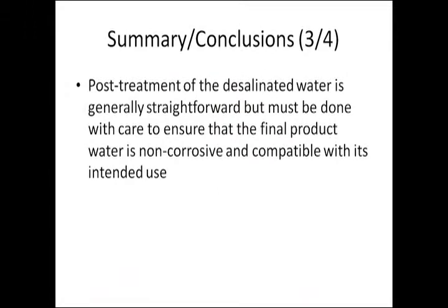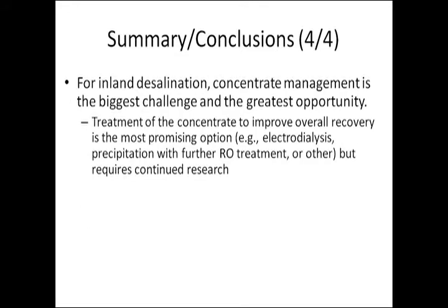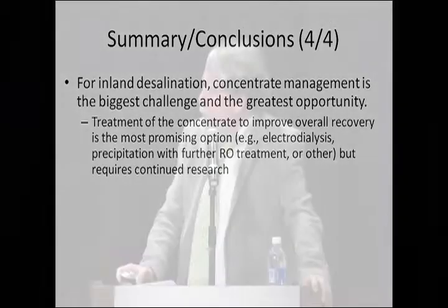Post-treatment is generally straightforward but must be done with care. I don't think there's a lot of opportunities for improvement. Well, it has lots of challenges and really few opportunities for improvement. And lastly, I think for inland desalination, concentrate management is the biggest challenge and also the greatest opportunity. Treatment of the concentrate to improve overall recovery is the most promising option. For example, electrodialysis or precipitation with further RO treatment, but it requires continued research and probably somewhat site-specific research.